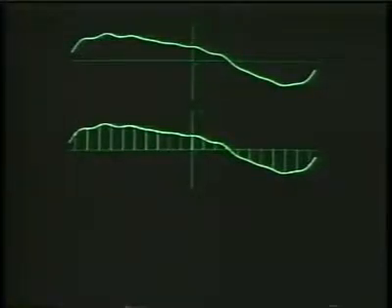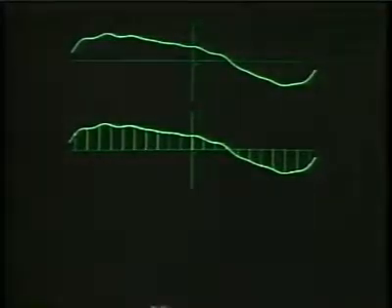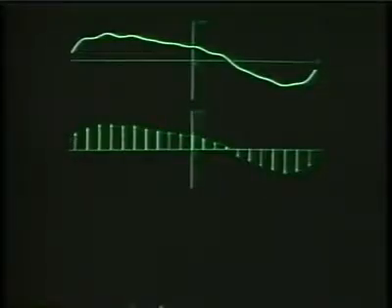Shown here first is the continuous time signal, which we want to sample and then reconstruct using band-limited interpolation, or equivalently ideal low-pass filtering on the set of samples. So the first step then is to sample this continuous time signal, and we see here now the set of samples, and superimposed on the samples are the original continuous time signal. To focus on the fact that those are samples of the top curve, let's now remove the continuous time envelope of the samples, and it's this set of samples that we then want to use for the reconstruction.